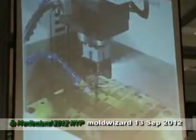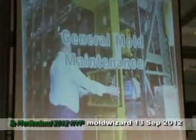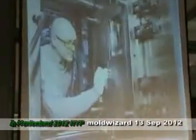Designing and constructing an injection mold can be an expensive and time-consuming process. Molds are extremely valuable tools that must be properly cared for before, during, and after production. General mold maintenance can help avoid costly repairs and retooling. Before a molding operation begins, the mold should be closely inspected for any damage such as cracks, leaks, or rust.